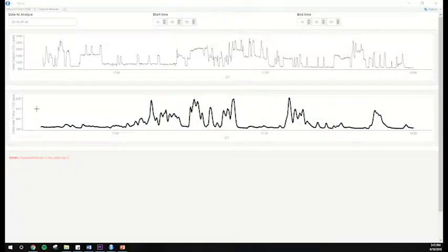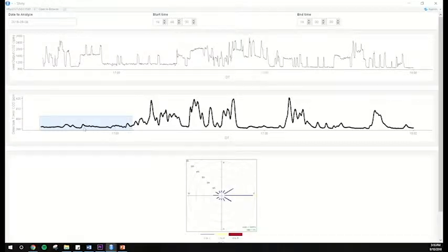Recalling that the detection tower is located due east of the vent, let's take a look at the wind-rose diagrams during periods of non-detection when levels of CO2 are relatively flat and near ambient. During each of these periods of non-detection, the wind-rose diagrams show us that winds are either predominantly coming from the east or are sporadic and variable, with winds coming from all directions. This indicates that air from the vent is not reaching the detection tower.